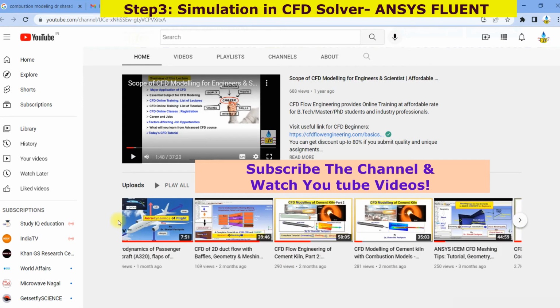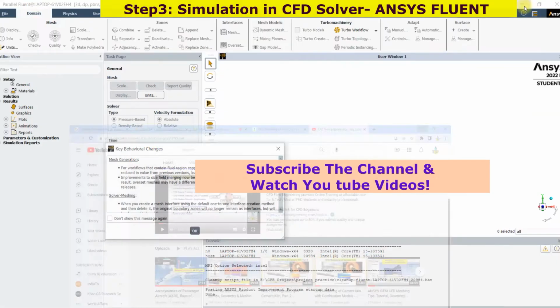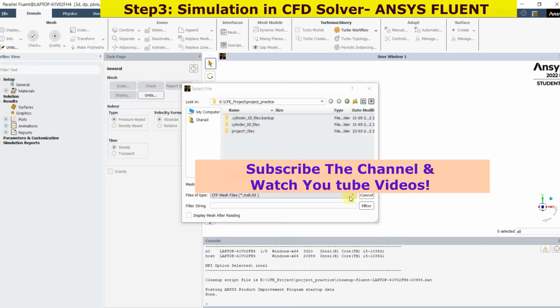After reading this mesh file, like cylinder.msh, read the file in .msh mode, and after this click OK. Please note that here we are solving a simulation in the 3D solver, and it is reflected at the top of the Fluent window. It is a 3D mode simulation, pressure based solver.